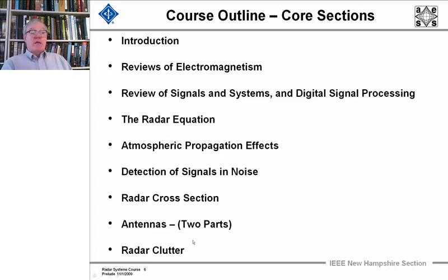Next, we're going to talk about antennas, which take the energy that a transmitter will generate in the microwave region, that electromagnetic energy, and focus it in one region so that you can focus that energy to see the target better rather than if the energy went all over space. And you'll obtain from the antennas usually a good understanding of the azimuth and the elevation of the target that you get the reflection from. That's a big part of the course. We're going to take 2 sections for that. Two what I call lectures.